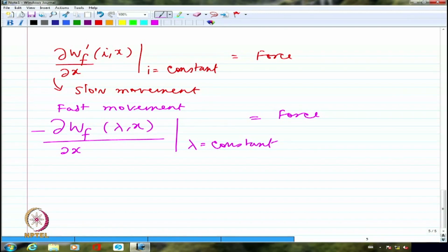But before that, whatever we have specified as lambda, we said basically this is n times phi, which is also indirectly L times i, provided we consider L to be a constant. If we consider L to be a constant, probably it is not going to have variable permeability even at a particular point.